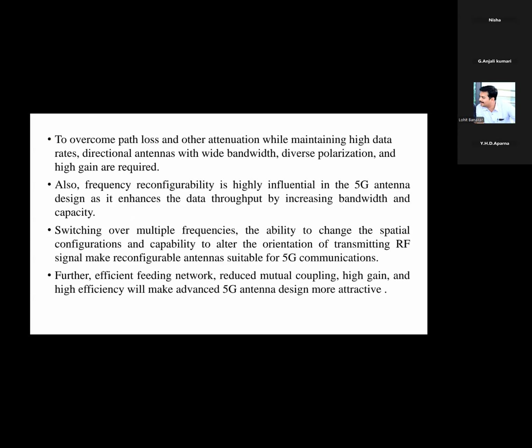Also, frequency reconfigurability is highly influential in 5G antenna design as it enhances the data throughput by increasing the bandwidth and capacity. Switching over multiple frequencies, the ability to change the spatial configuration, and the capability to alter the orientation of transmitting RF signals make reconfigurable antennas suitable for 5G communication. Further, efficient feeding networks, reduced mutual coupling, high gain, and high efficiency will make advancing 5G antenna design more attractive.